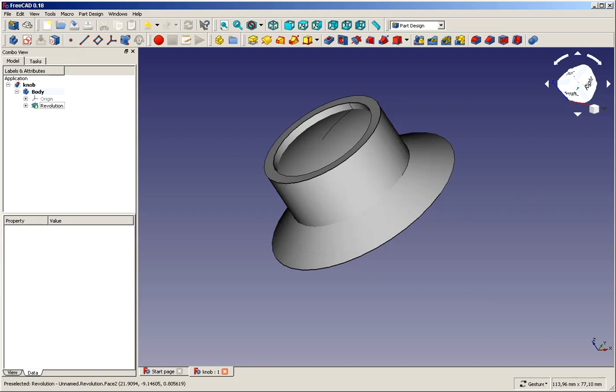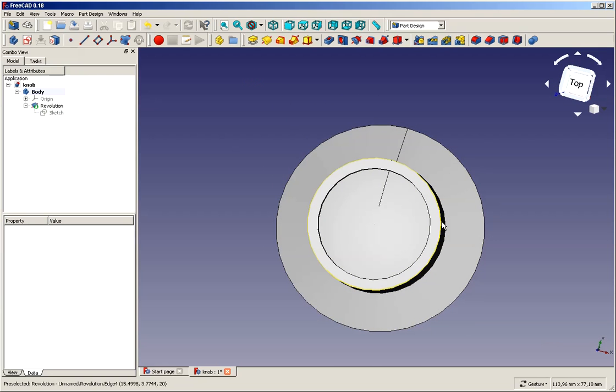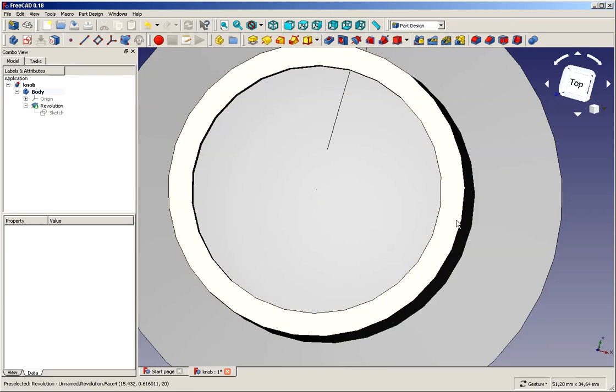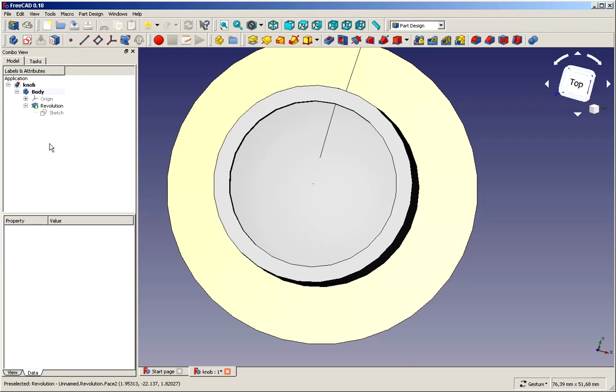Now we're going to create the sketch that gives us the detent, which cuts out a piece of our revolution. To make this sketch, we have to think a little bit. Finally, the detent should just cut out something here in a trapezoidal way. And to make this happen, so it cuts out exactly from the outline or from the radius of this circle, we have to construct it a little bit tricky. Okay, how do we do that?